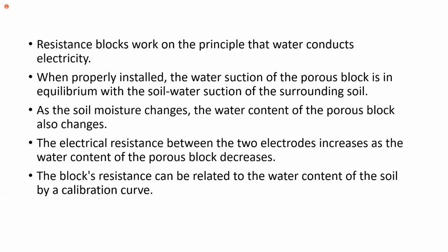The resistance block works on the principle that water conducts electricity. When properly installed, the water suction of the porous block is in equilibrium with the soil water suction of the surrounding soil. Once you install it and allow some time, the water potential inside the block and the outside soil will come to equilibrium.